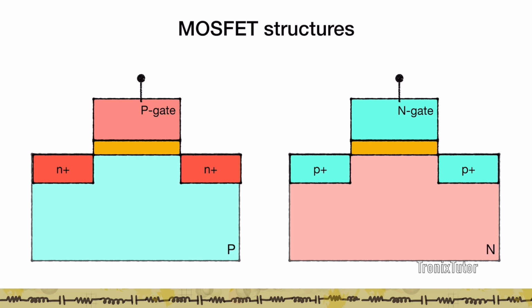The MOS structures are essentially as shown here. In this structure you have a p-type substrate and N+ source and drain, whereas in the PMOS you have an N-type substrate with P+ source and drain. In most cases the gate work function between the NMOS and PMOS are different, so I've indicated them as two separate colors which are specific to the gate of the P and the N. Ideally, when VGS is 0 in both cases, you have some sort of a depletion region, right?